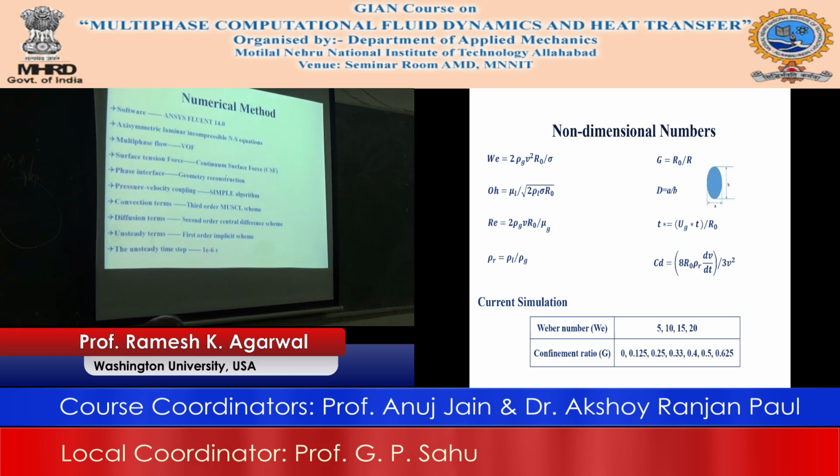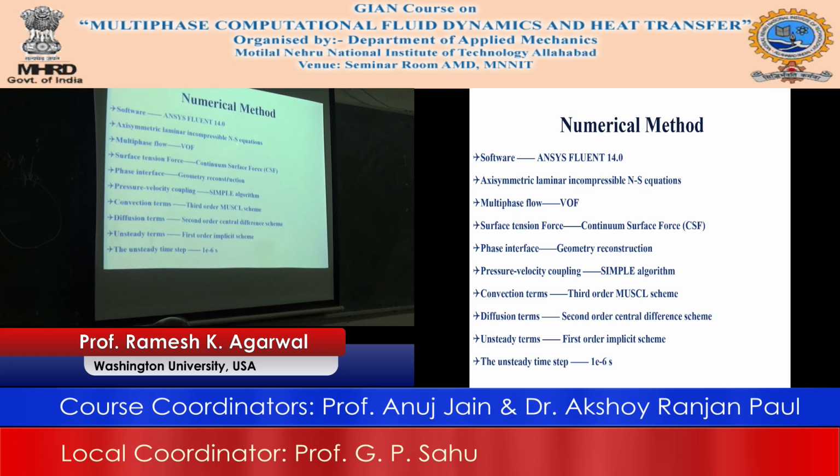Again, the numerical method is the same: incompressible flow, volume of fluid. This is important. For some reason, we tried very hard with the level set method to get a better interface, but the code always diverged. So it is again using the continuum surface force method, which gives a very good answer.